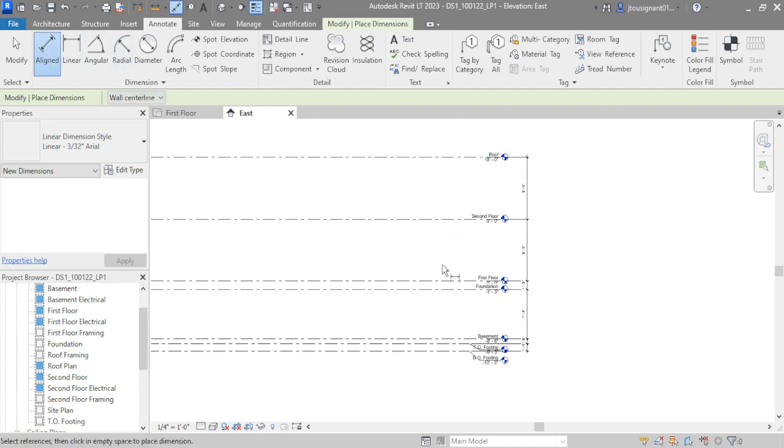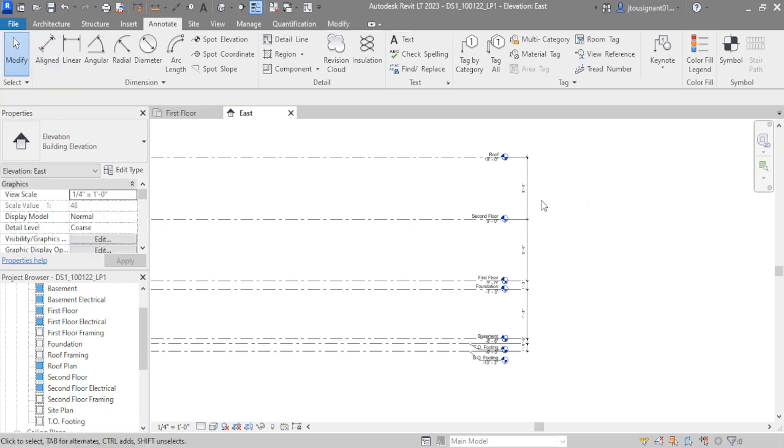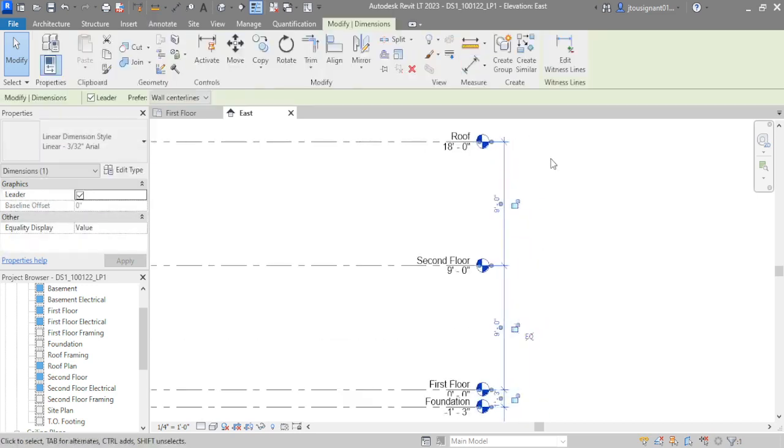And then I clicked on all these lines and then clicked in the blank space for my last click, because that's how you end the dimension tool. That is not intuitive with Revit. After a while it becomes intuitive, but when learning Revit, it is not intuitive to know to have your last click be in blank space.